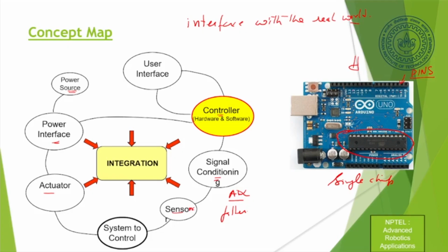If you connect a wire into pin number 1, then you know that whatever is the function of pin number 1, it will be doing that function only. For example, if it's an analog in pin and you connect an analog sensor there, it is going to take an analog signal in that pin. This is what we call a development board, and different companies make them.